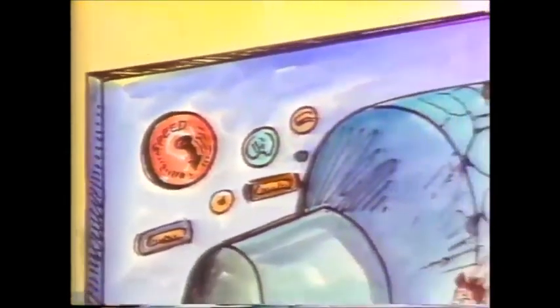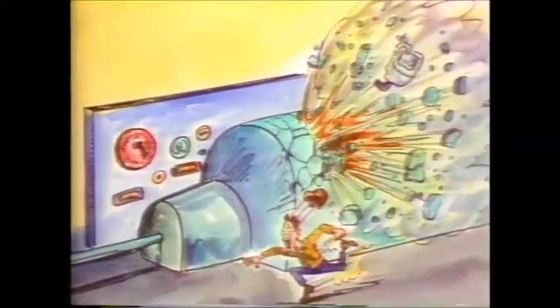Under certain unusual conditions, the turbine may begin to overspeed. That is, the turbine is turning at a rate much higher than it was designed to handle. An immediate danger exists that the turbine speed will increase to a point that centrifugal force will break it apart. This is where the reheat stop valves and intercept valves provide additional protection to the turbine unit.